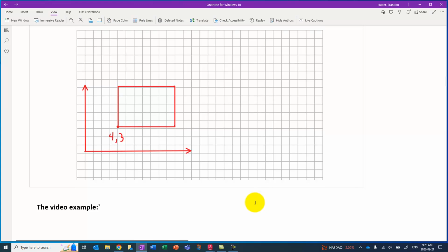So this will be our first drawing, just a simple rectangle. We're going to approach it much like we did with absolute and relative coordinates. So we'll just kind of type in the points first. The first thing we would do to draw this is type L for line and then enter. Our first point would be an absolute coordinate, so 4, 3.